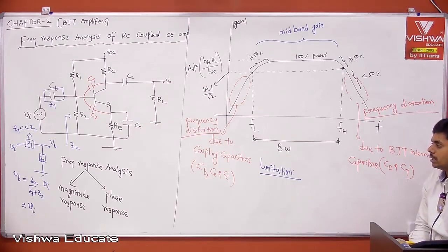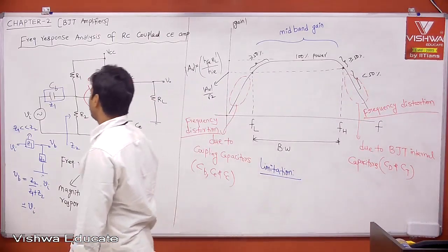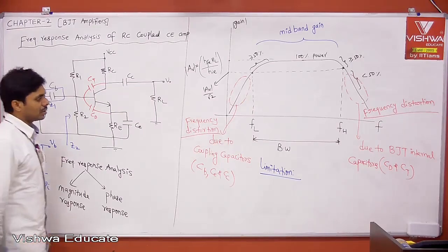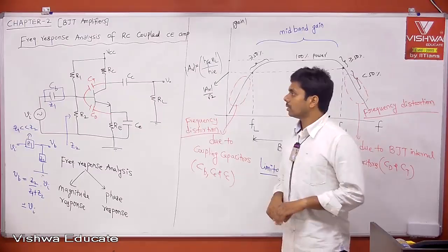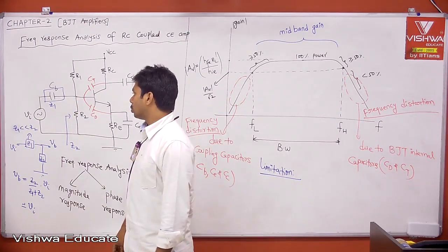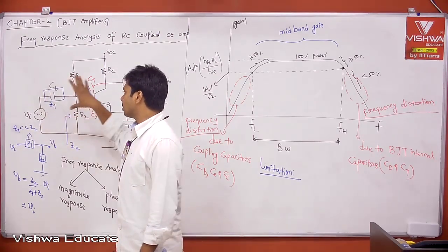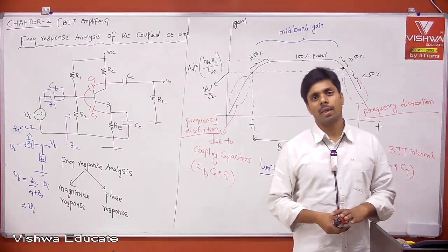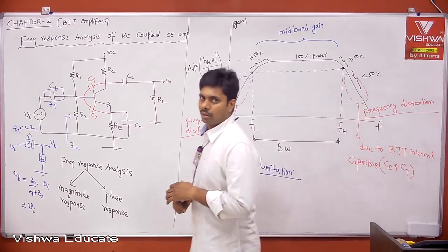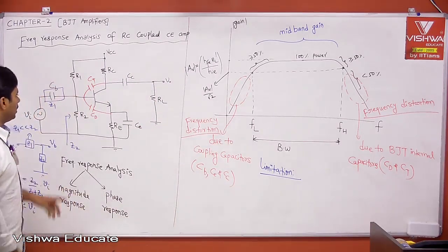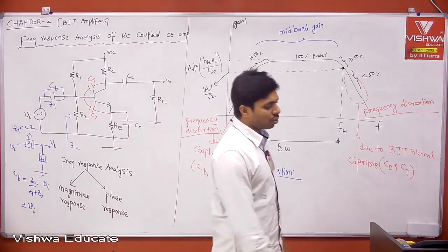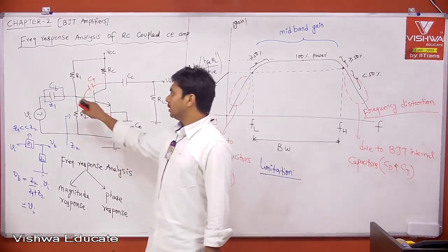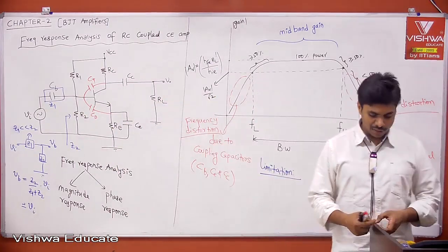CB, the input coupling capacitor CB. Write a note. First point: the coupling capacitor CB couples the input AC signal to the transistor input, and blocks the input DC bias voltage. I'm just explaining the functionality.